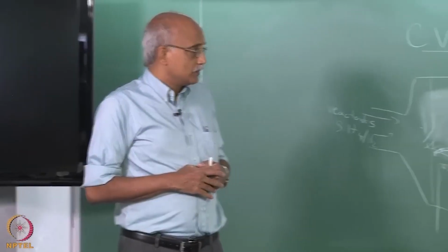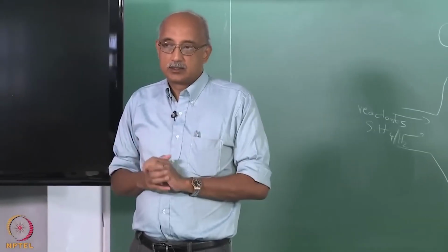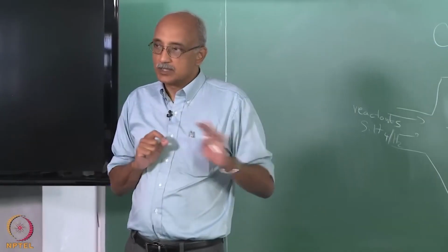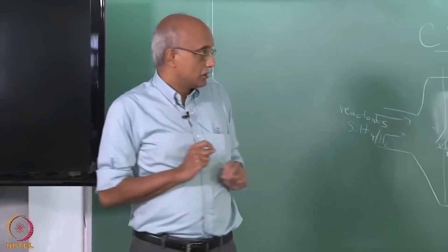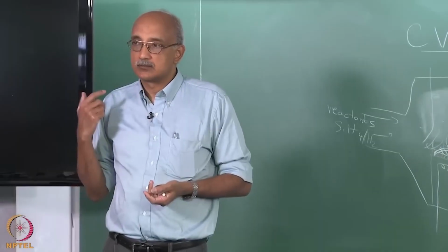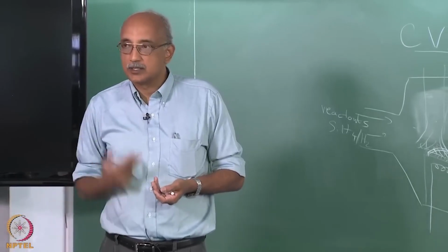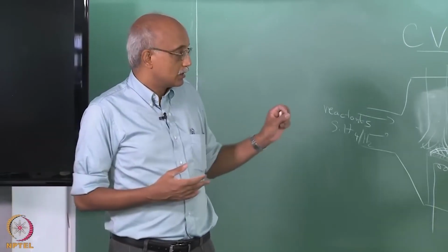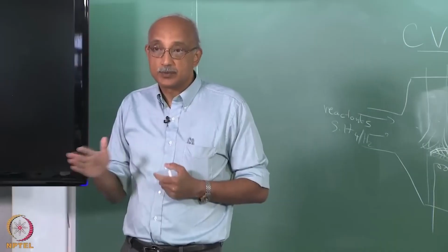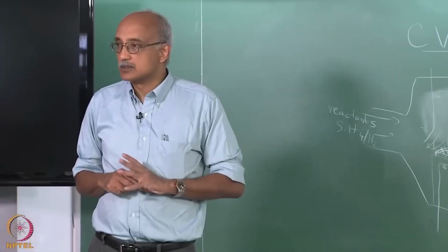Okay. So, if you look at these various steps that are involved in the CVD process, you get a feel for why chemical engineering is such an important discipline to apply to the design and operation of a CVD reactor. Each of these steps involves again either equilibrium thermodynamics or chemical reactions and kinetics or transport phenomena of various kind, various control mechanisms. So, in order to achieve a CVD film on a surface, which sounds simple enough in principle, you have to pay attention to many of these mechanisms.